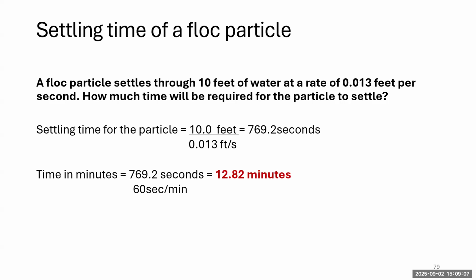The detention time for sedimentation basins is generally between 3 and 4 hours. However, the surface area can affect how much time. For example, if you had a tank with a ridiculous shape, 5 foot in diameter and 200 foot tall, that's not going to allow much settling time at all, even though it has all that extra depth.